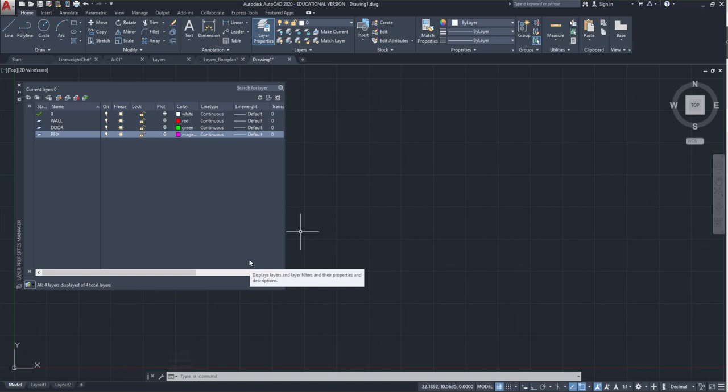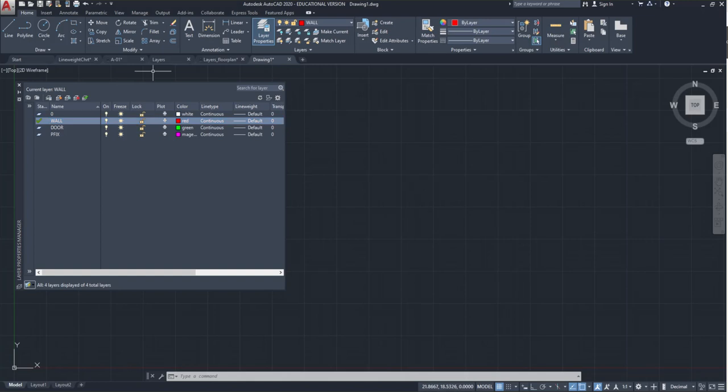Now it's time for me to draw. I want to draw a wall. So I'm going to double click on my layer here. Click on my line and get drawing. Click, move in the direction I want to go. Ortho is F8. 10. I'm in decimal units. I made a mistake, so I need to change to architectural. So 10 foot, enter. Escape, escape, zoom extents.